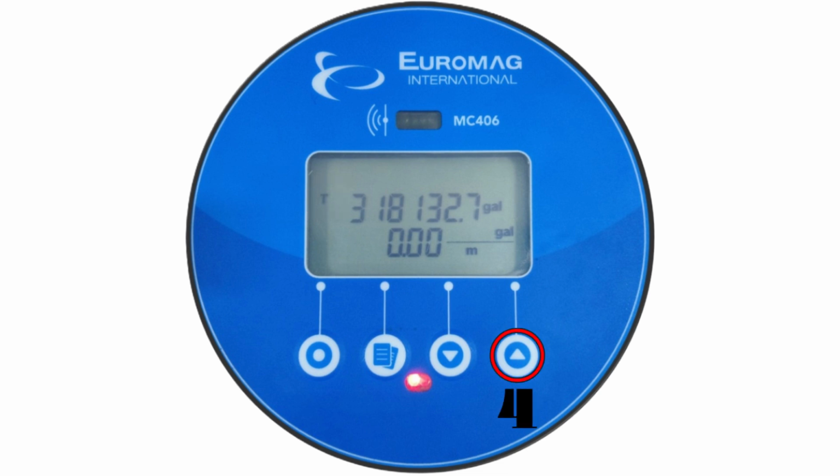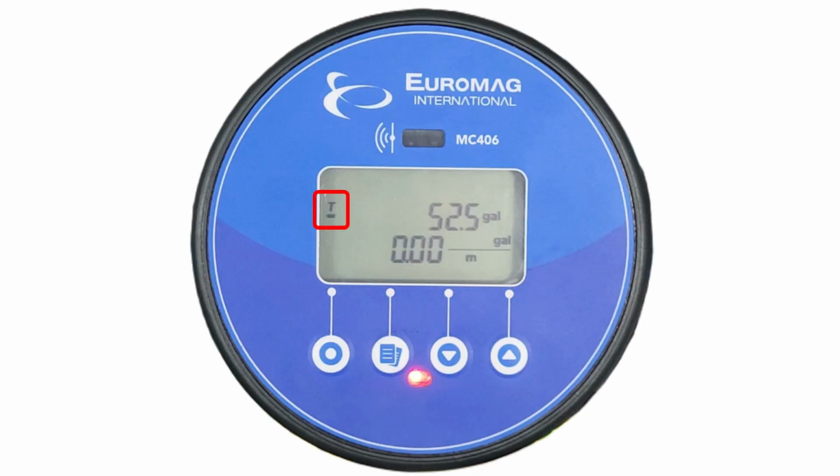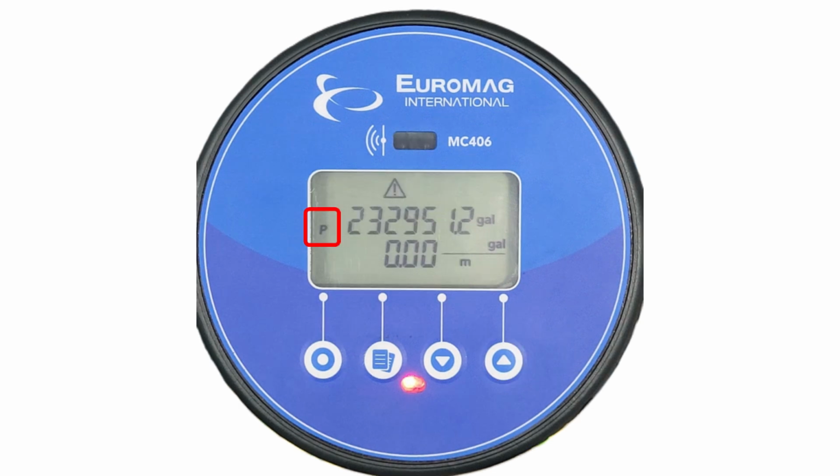Pressing the number 4 button will change the T to a T with a negative symbol below it. You are now viewing the total flow that has reverse flowed through the meter. Pressing the 4th button for a second time will change the T negative to AP for partial total forward flow. The partial totalizers can be reset back to 0.